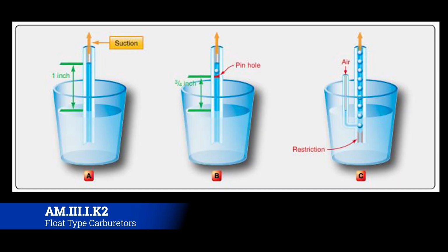Okay, so let's talk about the air bleed a little bit. All the air bleed is effectively doing is helping your carburetor run with the appropriate level of mixture at low idle speeds, with either more air or less air to make it richer or leaner. Now the air bleed screw will come in or come out, allowing more or less air into it, and so the more you screw it in, the smaller the orifice gets, or the smaller the space for air to come in. So therefore, the richer it'll run, because you're putting more fuel in the line as opposed to the fuel air mixture. Whereas if you open it way up and let a lot of air in, it's going to lean that mixture out.